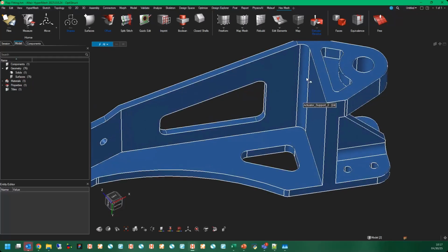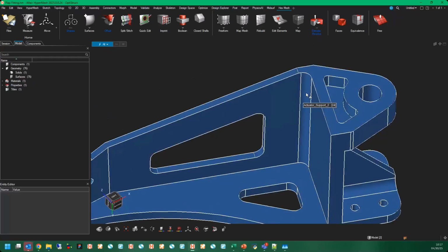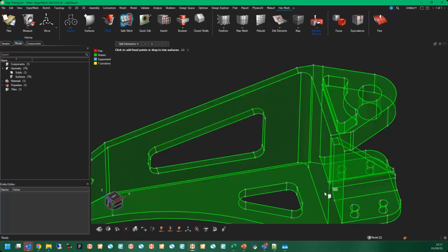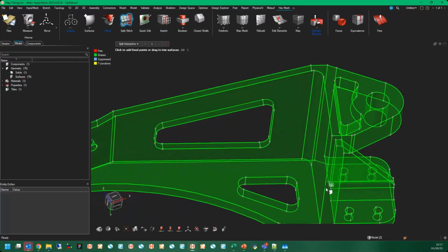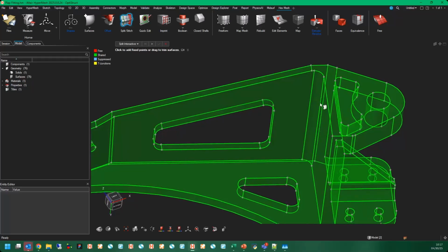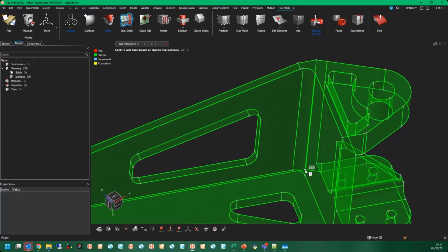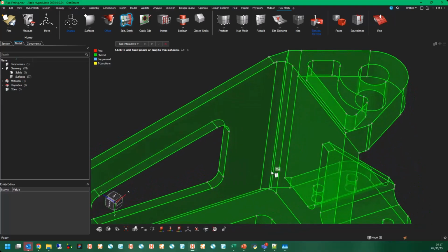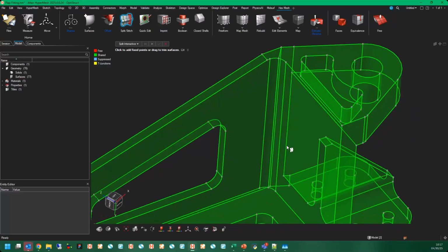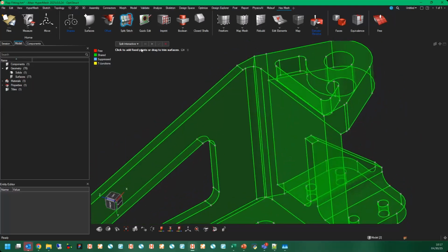And so when you encounter something like this, a good trick for adapting to fillets is, rather than just splitting along a plane that would be this surface, I like to split the fillet, and I do that by splitting the edge first. If I hold control, I can jump over to this edge or to that vertex. So I'm going to come across the face where it's flat here, but then come out halfway into the fillet and then jump over here. And that's going to be my splitting plane, so to speak.